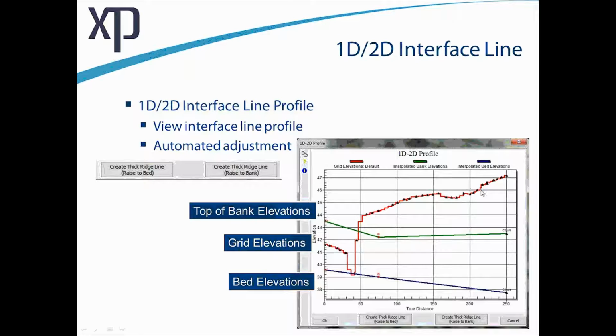And you can see in this example it's not ideal and not what we would expect. We wouldn't want to see the 2D surface ideally too far from our bank elevations here, and in particular with such a dramatic drop in this case, it shows how far off the actual values in our 1D model we are with those 2D levels.